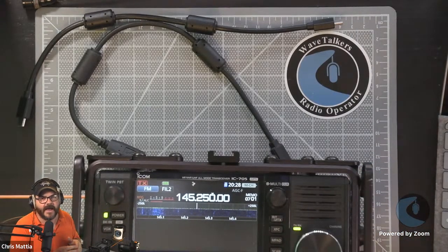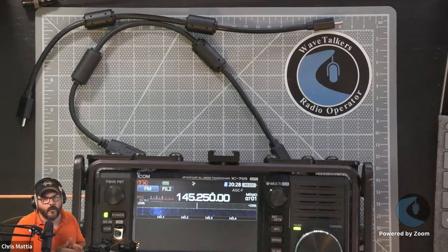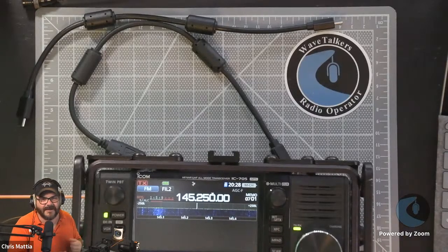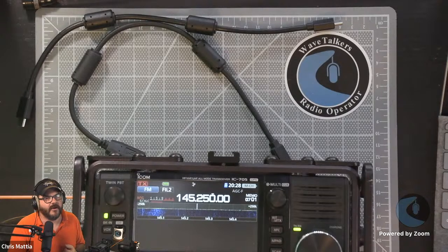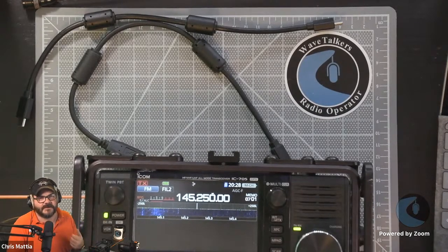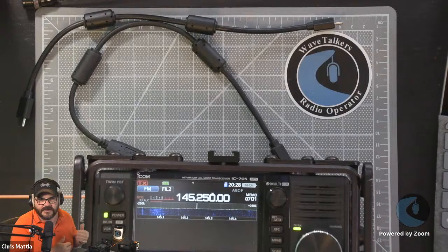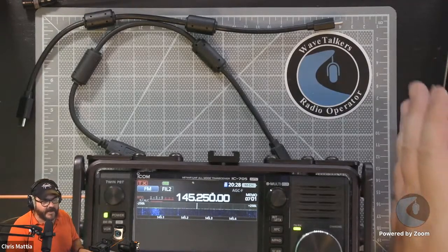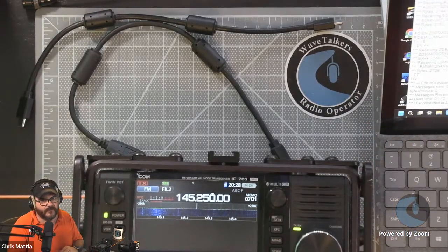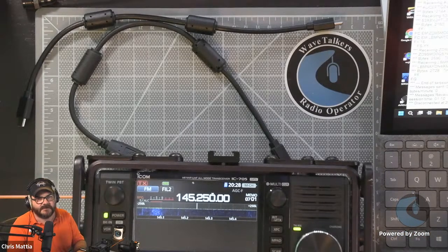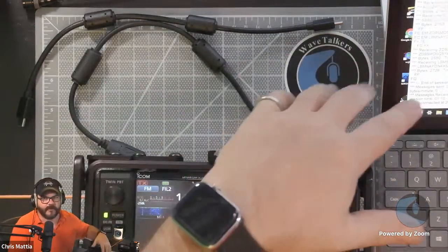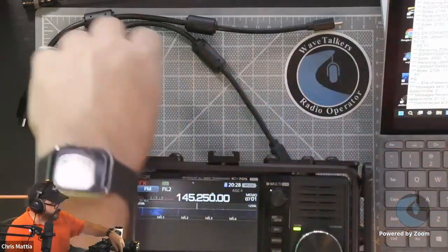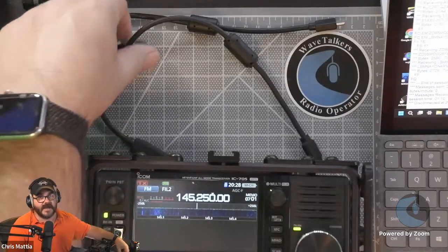And it took me a while to find a cable that would actually work with my 705. I went through a lot of different cables in the collection of cables that I had, and many of them just flat out would fail in that way that you're describing, where they just wouldn't transmit. Usually what was happening, as soon as it would start to transmit, you would get all this noise that would come back through the radio. And a lot of that, for instance, my Microsoft Surface is really bad about pushing RFI out of its USB-C port and back into the radio and causing issues. So a lot of it is coming through the various different computers that you might have. It could just be picking up and using these cables as an antenna.